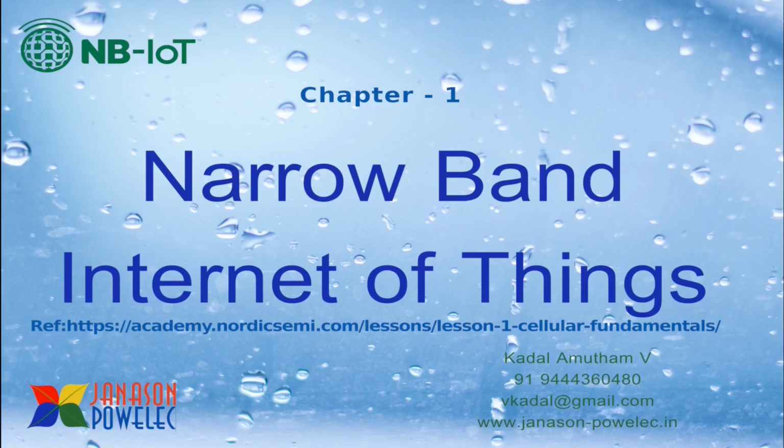NB-IoT is becoming more and more relevant in the coming days because many telecom operators are not going to support 2G and 3G. So if you want to form a wide area network covering many kilometers or even entire pan India, then NB-IoT is one of the most suitable options, provided there is cell phone coverage in that area. If there is 4G signal coverage in that area, then NB-IoT suits best for connecting devices to the internet.